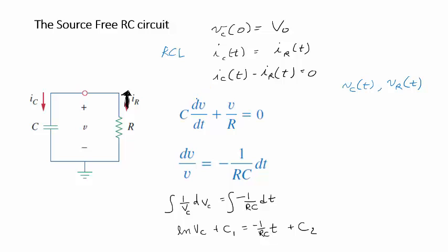So we have one variable here, voltage, that is the variable in this differential equation. Note I have one derivative right here. There's not a second derivative, so that makes this a first order differential equation. I've written my first order differential equation just by substituting what current is from our KCL relationship. Now I can rearrange the terms so I get the constants and dt on one side, and then I have 1 over v on the left side times dv. And I can integrate both sides with an indefinite integral.